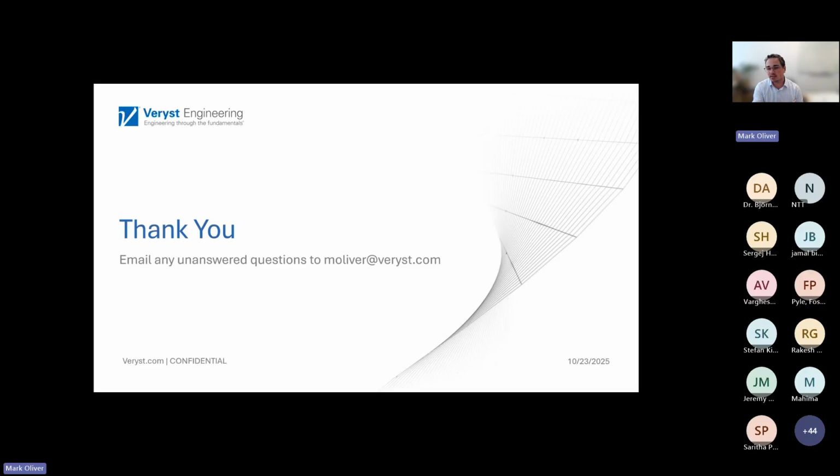And then you simulate those tests with the mesh that will actually be used in the final analysis. Often what you see is as you go to coarser meshes, you'll start to lose energy, and so you'll have to do a mesh compensated model definition.